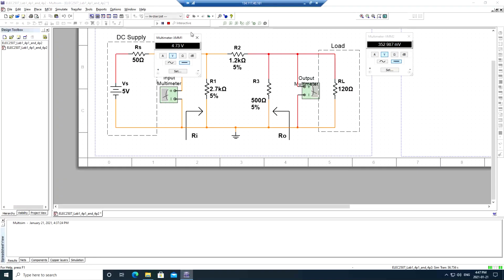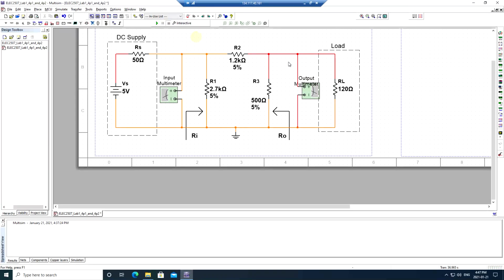So once you're back in the simulation, go ahead and stop it for now. And then you're going to hit Control-Shift-W again to place a wire, right? Because we want to short the output. So we want to just place a wire between those nodes, just like so. And once we have that in place, we can go ahead and rerun the simulation once again, and I put what's called a current probe here. So the A signals current, and I can see that I have a certain amount of DC current running through that branch, and that is virtually my I short circuit.